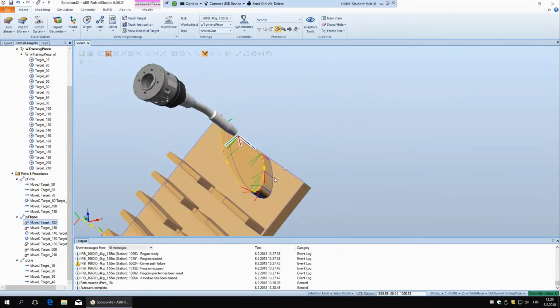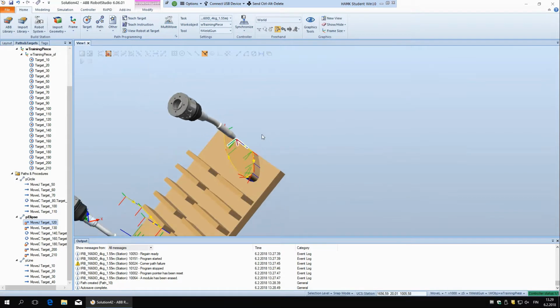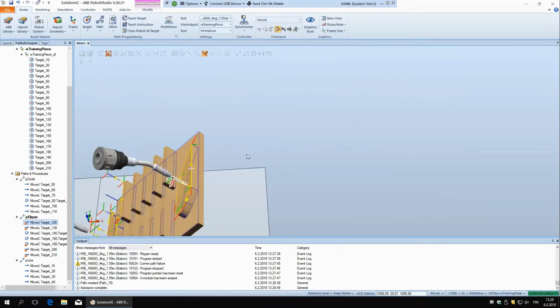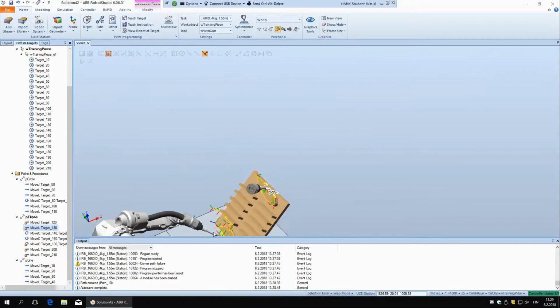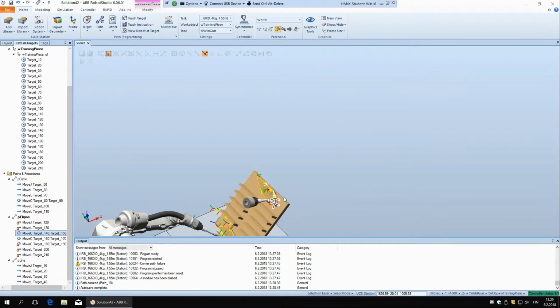Most likely they are. The problem is that the robot would have to be in some strange position. So yeah, like it's pointing this way. We are going to have to make it like that, same as what we did here with these targets on the line, so that the x-axis is pointing downwards. So these two, it can reach, yeah, they are down, and so they're pointing downwards.